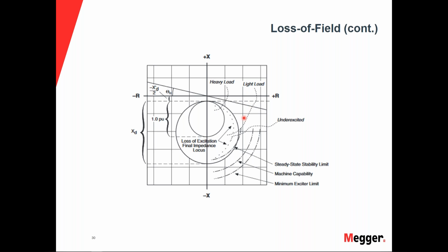In the lightly loaded case, if we're only using this for peaker generators or something that just has a light load as a supplemental to the system, then it gives you a little bit more time when it breaks into zone 2, before it actually gets into zone 1. Hopefully it doesn't, but generator protection has to take all precautions to protect the equipment itself.